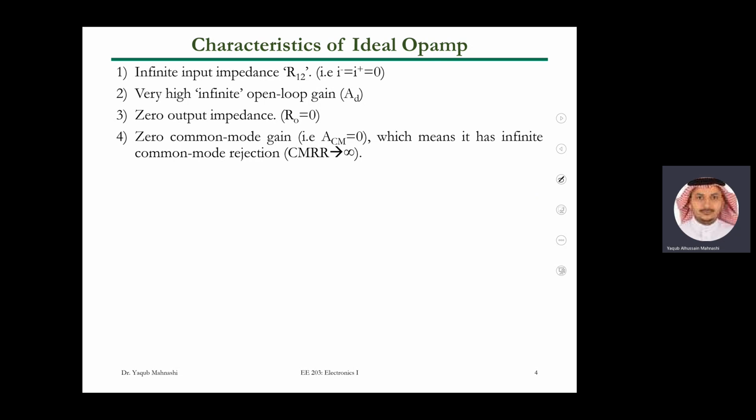Can I process a 1 megahertz signal? Can I process a 1 gigahertz signal? Can I process a 10 gigahertz signal? And so on and so forth. If you have infinite bandwidth, it can amplify any frequency from 0, which is DC, until terahertz, right? And this is the case with an ideal amplifier. So in ideal op amps, we assume there is infinite bandwidth.